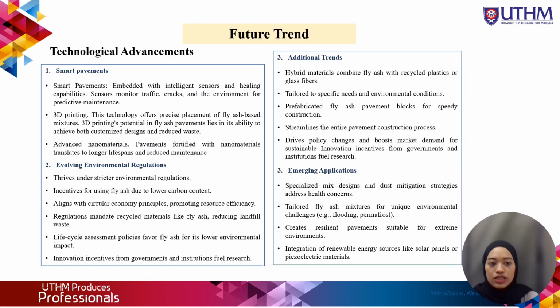Okay, for the future trends, the technological advancement. The first one is smart pavement. Smart pavement is embedded with intelligence, sensors and healing capabilities, which is sensors monitoring traffic, cracks, and the environment for predictive maintenance. Next is 3D printing. This technology offers precise placement of fly ash based mixtures, and it achieves both customized design and reduced waste. Next one is advanced nanomaterials. Pavement fortified with nanomaterials translates to longer lifespan and also reduced maintenance.